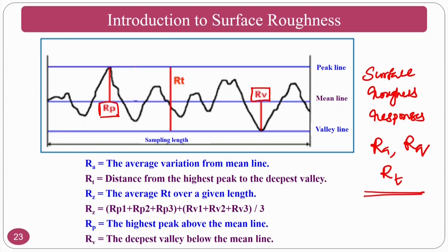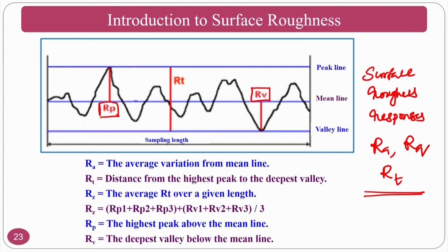If somebody is doing research in the metal cutting area, you can consider this on the workpiece with respect to feed, depth of cut, type of cutting fluid, and the speed of your workpiece, that means workpiece rotational speed or cutting speed. You can vary it. It's one of the good parameters because customers always want better surface roughness.